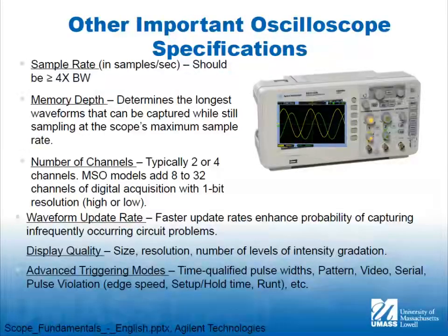How many channels, right? Oscilloscopes are usually 2 or 4 channels. But if we have a logic analyzer, it's very likely that the logic analyzer has between 8 and 32 channels, right? Or more. But remember how hard I was making it out to be to get those 2 probes on 2 adjacent pins of a big IC. What's going to happen when we have to connect 32 of those? It very quickly becomes prohibitive.